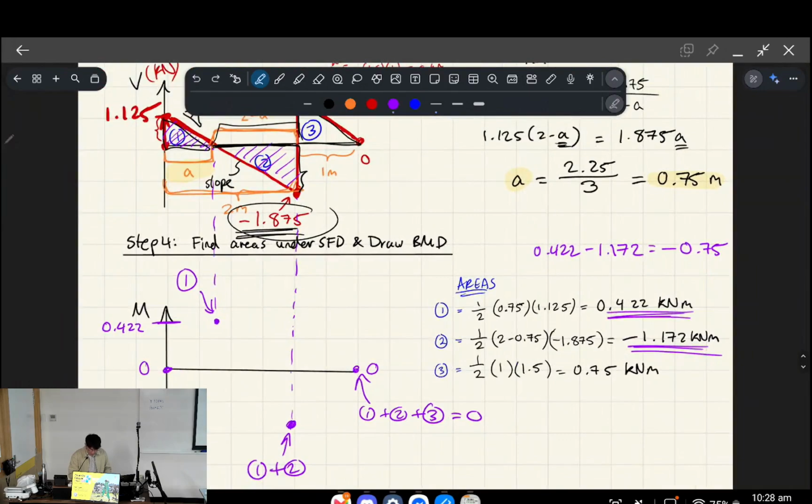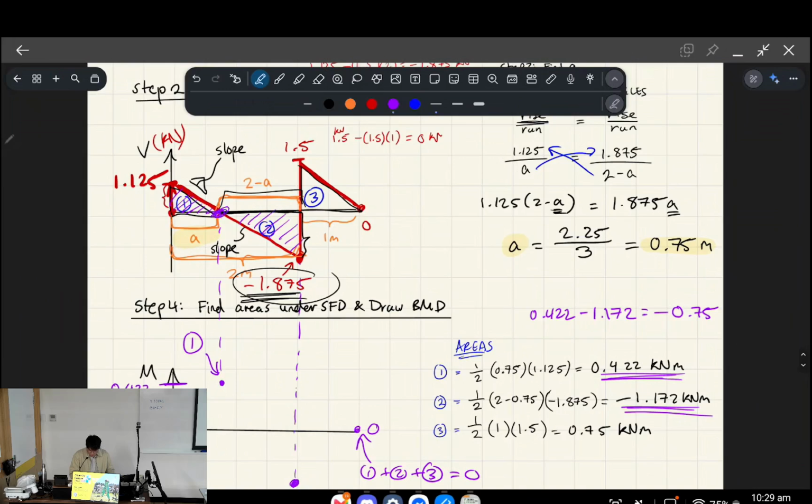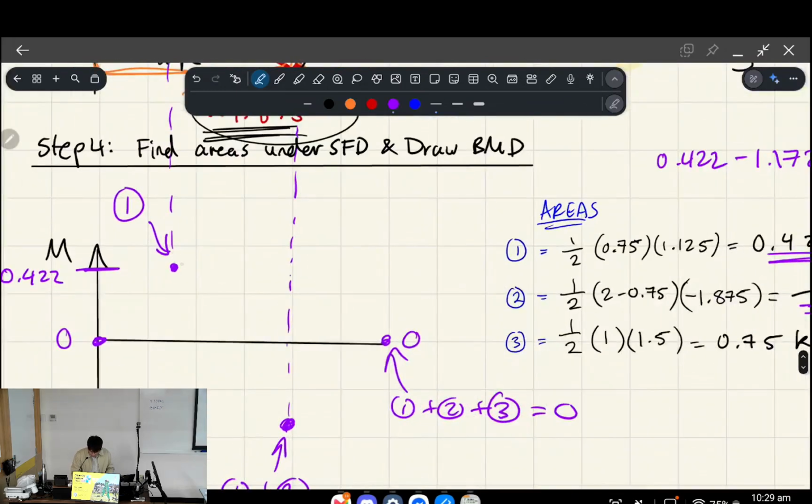Now, one thing that's pretty useful to realize is that when you have 0 shear force, aka when the line intercepts the shear force equal to 0, the parabola is going to be flat at that point, okay? The slope of the parabola. In other words, you can expect it to be flat here, and you can expect it to be flat here, okay? I might do that in a different color. So it should be flat there and flat there, okay? That's the first hint that you have.